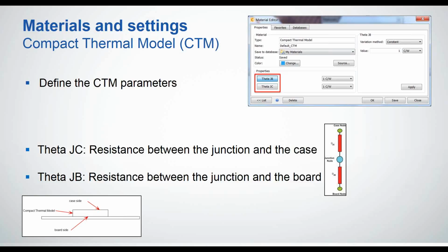If you are rather interested in seeing the global heat transfer inside the whole model, and you're not interested in this component, you can just model it as a solid, and then apply the total heat generation as a boundary condition. Actually, the total heat generation boundary condition, you can use it either when applying a CTM or a solid. But this depends, after all, on your end goal.